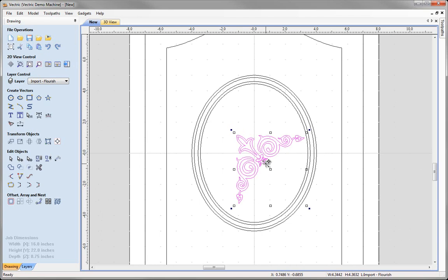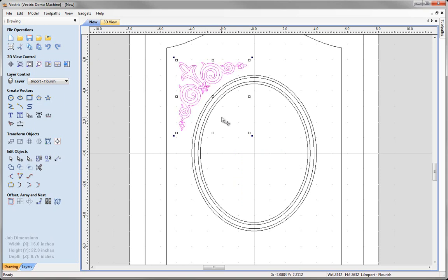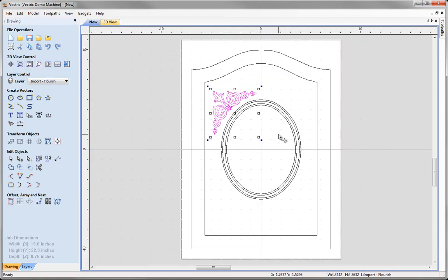I'm going to come to the point in the corner here. You can see the cursor showing me I'm snapping there. I'm going to click on that and I'm going to move this and snap it to this node here, to this point here on the snap grid. So we're just going to click on that, move it up, get it so it's snapping there, and then I can let go, and now that's moved that to that new position. And again, we've used the snap grid to help us to locate that. Now I'm going to come back and click on the zoom to fit icon. We can also use the shortcut key F on the keyboard in order to zoom the 2D view into the window space.